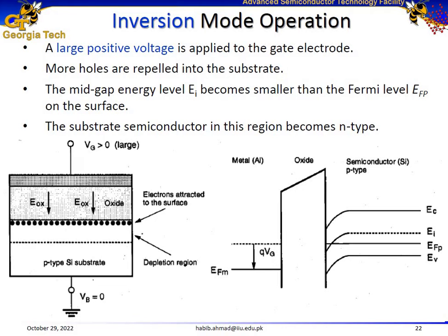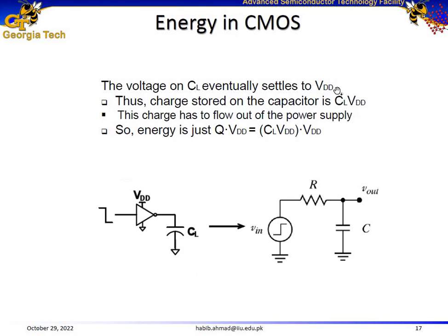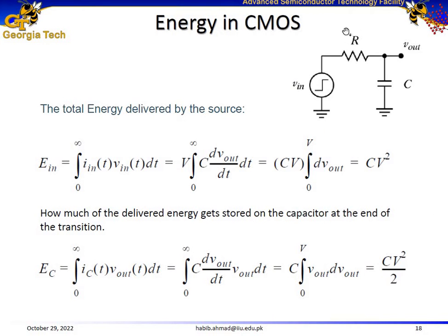If you increase voltage, the current is increasing. So that means that this channel does have a certain amount of resistance as well. And our resistance from this model of RC network comes from the channel. The capacitor comes from different sources, which we already discussed in chapter number 3, but the resistance comes from the channel.